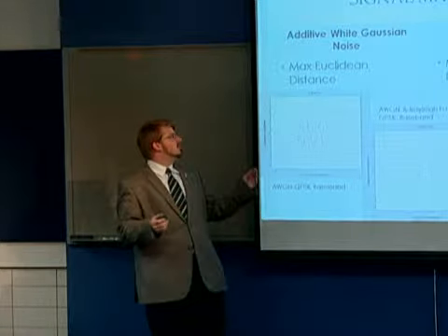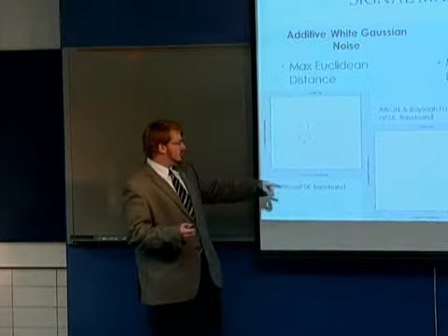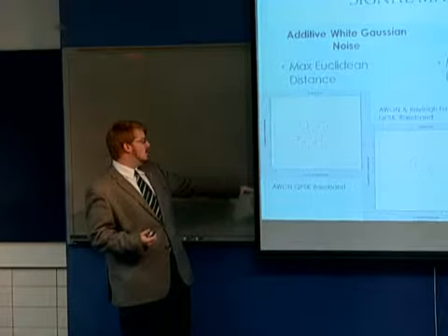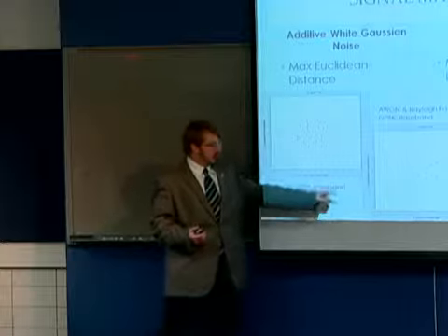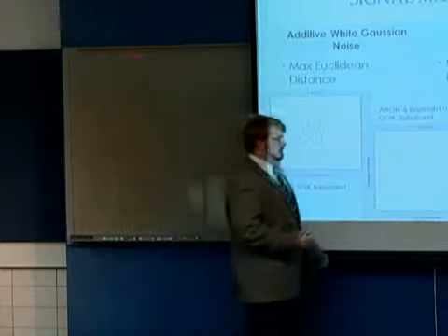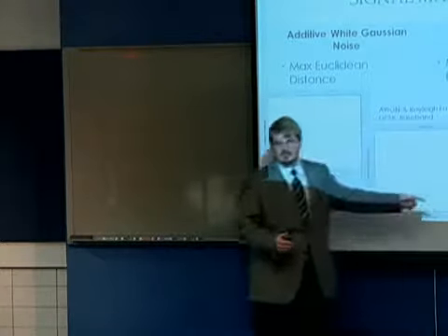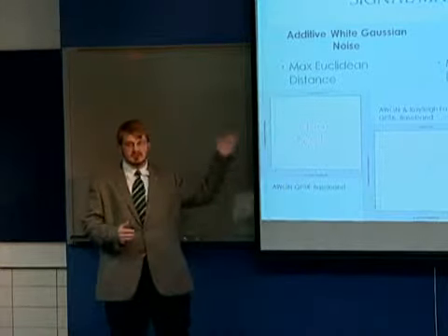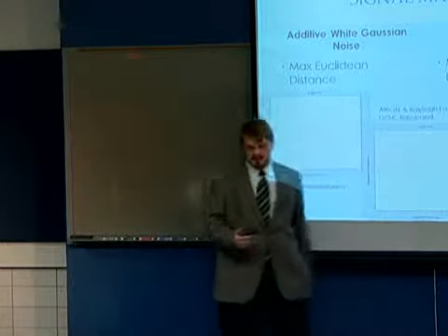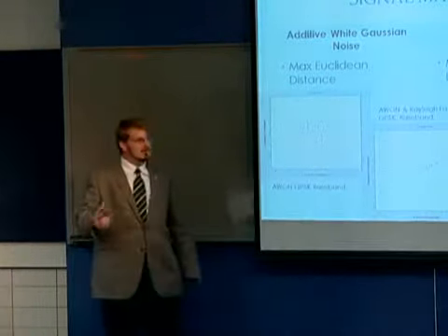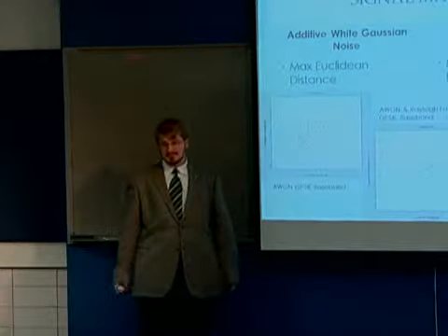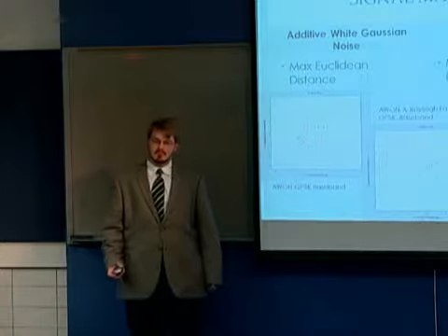And then just little constellations of these are QPSK. This one's additive white Gaussian noise, a mixture of both, and then Rayleigh fading. And you can see the different effects. With this one, we actually took out the phase, and that's why it has a constant phase practically. And the speed at which these points move up and down depends on whether it's slow or fast fading.